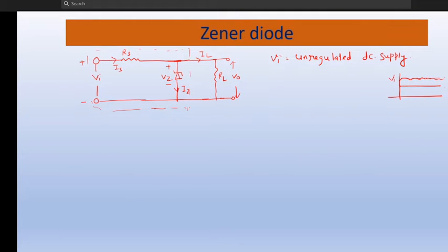So when such issues occur, suppose we have this DC supply, like the charger you are talking about, laptop charger and mobile charger, we say this is a DC, right? But why am I saying it is unregulated DC? Because it has got some ripples. Ripples means some AC components are present in this, right? Ripples means just like this kind of, right? It's not pure DC. There are some ripples in the input. So because of that, your device may get damaged.